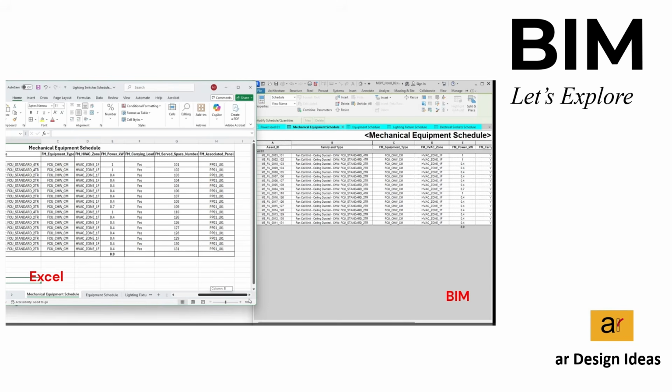In this series, we are not trying to model everything. We are deliberately modeling only what facility management actually operates, monitors, and reports. This episode focuses on low-side electrical systems, modeled from an FM point of view, not a construction one. We stop at the panel level. We capture assets, their power, and where they belong. And we ensure that the data exported to Excel is not recreated, but mirrored directly from the BIM model. I'm BIMThinker, and let's explore.